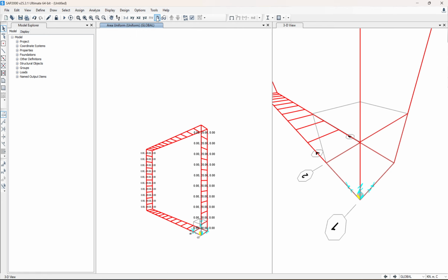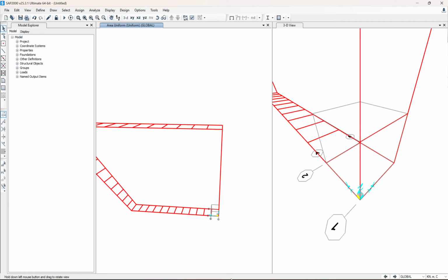And similarly, whatever the soil above, you can apply. Usually the soil above would be uniform pressure, but in this case, for the vertical elements, I only applied a uniform load for the time being. Realistically, you need to apply them in the actual way. Say, for example, it's increasing.